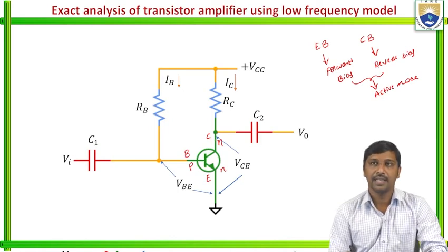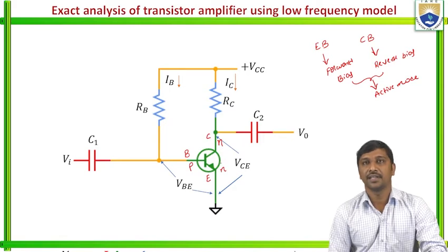The collector is made with N-type material, so it is also biased with the positive pole of the battery through a biasing resistance, represented as RC. Hence, the collector base junction becomes reverse bias. From this biasing, the transistor acts in the active mode of configuration. Hence, this transistor acts as an amplifier.